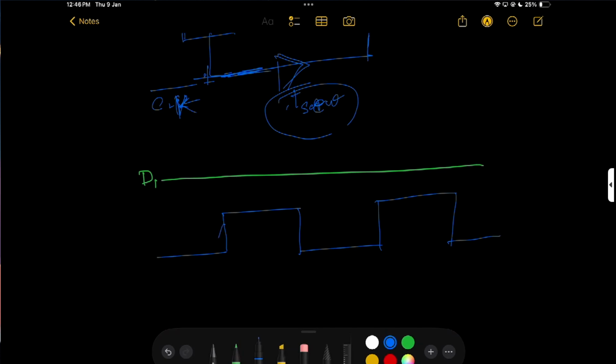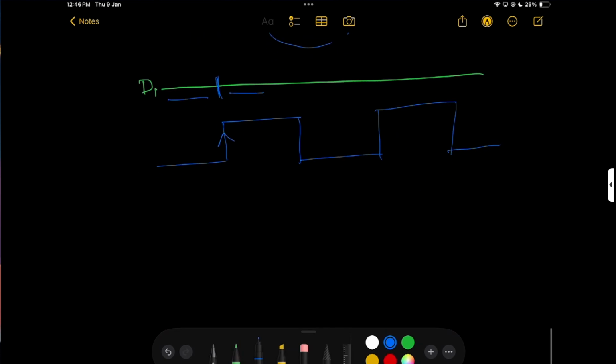Okay, so in this period, at the positive edge of the clock, just check whether my D1 setup time or hold time is violated or not. It's not violated, so it gives the output, but in how much delay that will take, after that this output will be shown at Q1. So here suppose my output is like this. Again it comes to here, so it will check again. That time also we output one.